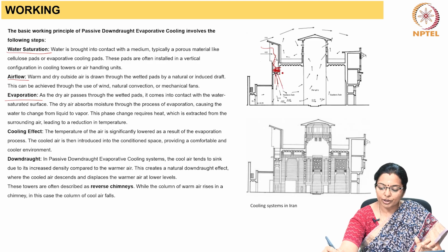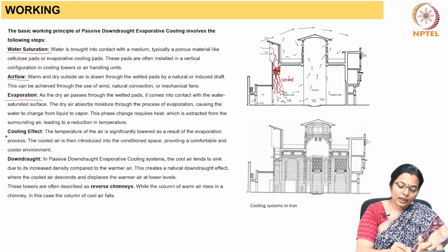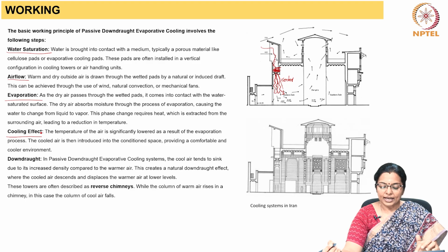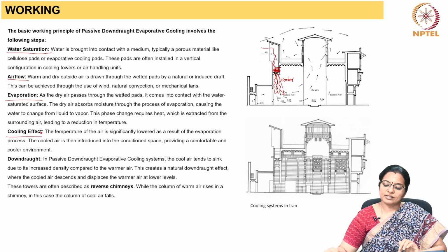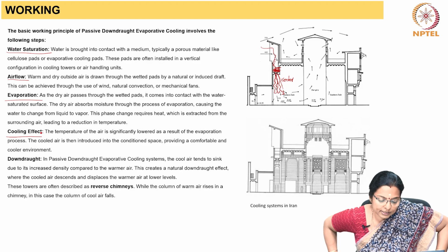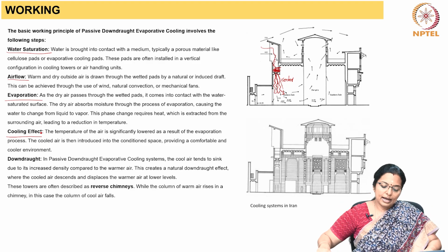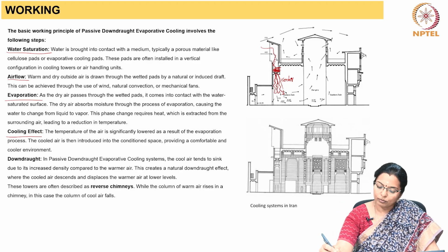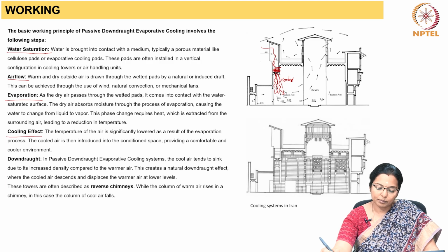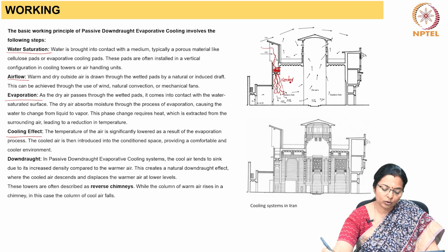This phase change requires heat, which is extracted from the surrounding air, leading to a reduction in its temperature. So, the air which comes out is cooler. The temperature of the air is significantly lowered as a result of the evaporation process. The cool air is then introduced into the conditioned space, providing a comfortable and cooler environment.